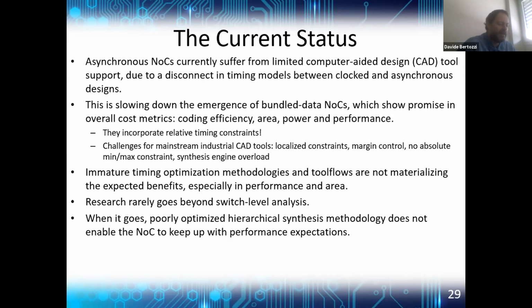Another disconnect is that CAD tools, I already talked about this, typically support only absolute minimum delay constraints. But in this case, the data path delay to be matched can be known only at synthesis time. Last but not least, due to the proliferation of local timing constraints in an asynchronous design, the risk is to seriously overload the synthesis engine, thus failing design convergence.